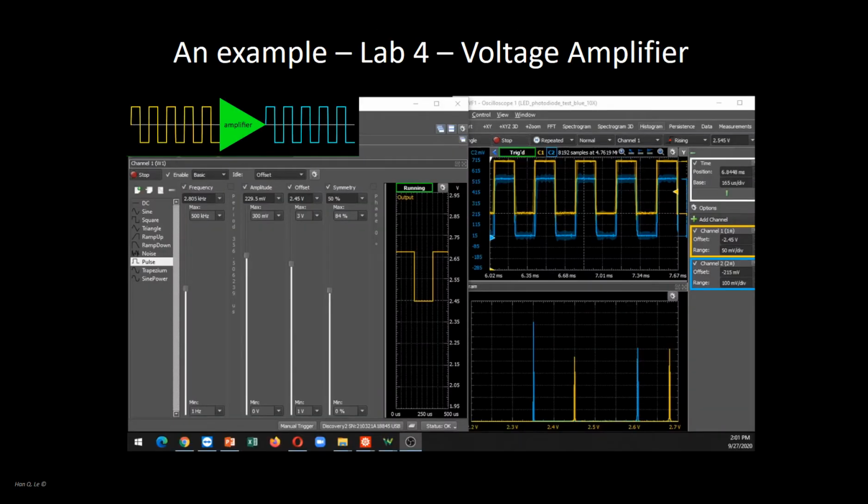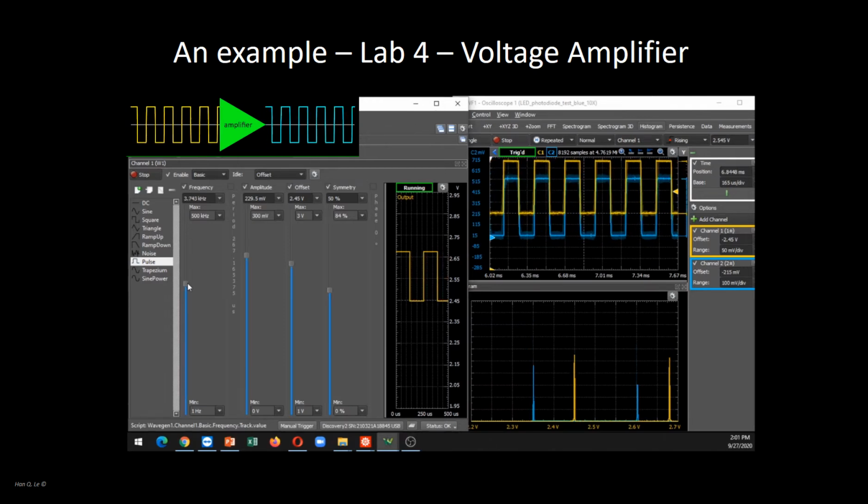This is a specific demonstration of the concept, which was also shown in Part Introduction. A square wave is input into the voltage amplifier. The input is represented by the yellow scope trace, the output is represented by the blue scope trace. Although sinusoidal signals should be used for the actual measurement, square wave can give a better insight.